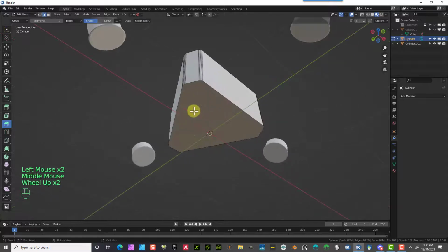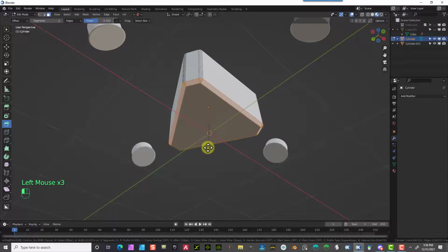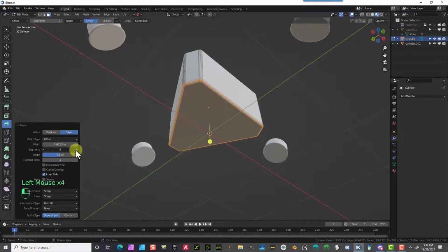Okay, hide everything else. I'm going to go in there and actually modify the base. Hit polygon. And I'm going to bevel this in, not too much, because it's going to overcut if I do too much. Add some segments.